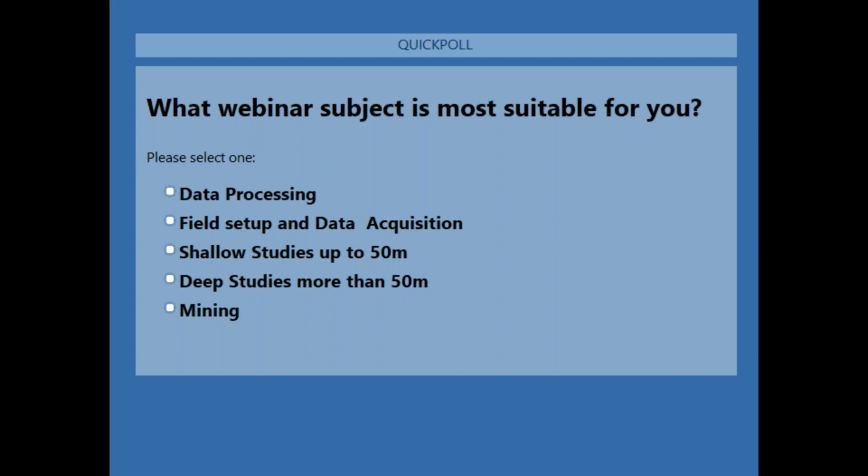Okay, how does the expansion factor change depth of image? That's all related to the geometric factor, which depends on the array type. The array type we recommend is dipole. For depth of penetration with that, in a marine, saline water environment you will get about 15% of your total cable length, and 20-25% on land studies. So just consider it that way. You don't need to consider a different geometric factor or expansion factor.